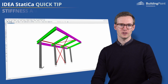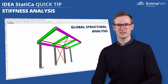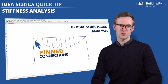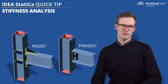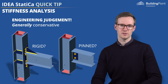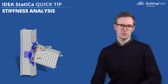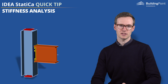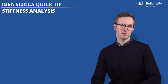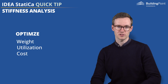When you perform a global analysis of a steel structure, it is common to assume that the connections between the members are rigid or pinned. This is a choice you make in the global analysis based on engineering judgment, and it is generally a conservative approach. Sometimes, though, there is flexibility in the connection between the members that you can take advantage of, if you can quantify the stiffness. It gives you the ability to optimize with regards to weight, utilization, and cost.